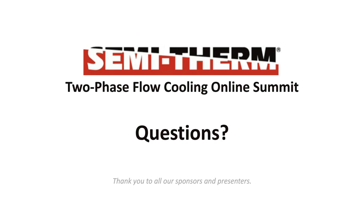Okay, our next question is how to join the metal foam with a solid metal? There are different ways you can do it. If minimizing contact resistance is a primary concern, as in many heat transfer applications, brazing is preferred. Another way to do it is with soldering.